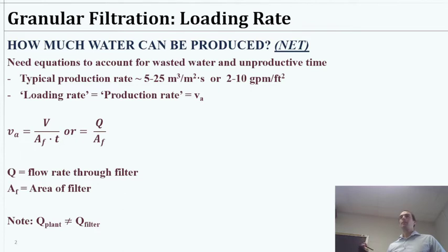If we can take some offline and we have enough production outside of that, that's the ideal case. So we don't have any moments where we say, oh, sorry, you don't get water today because we had to stop and maintain a filter, right? And it's even better if we have enough redundancy to say, oh, we were not expecting to have to maintain that filter, but now we are. So we usually design it with some safety factor as well.